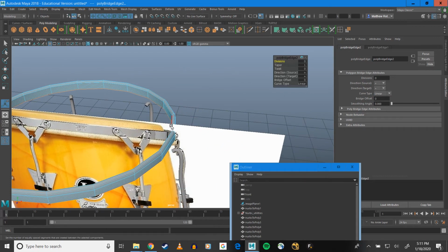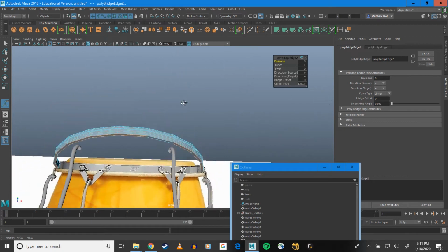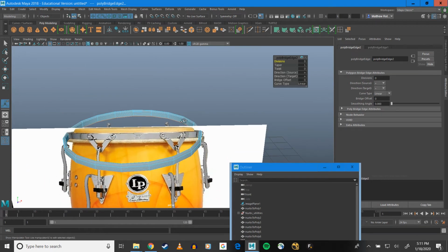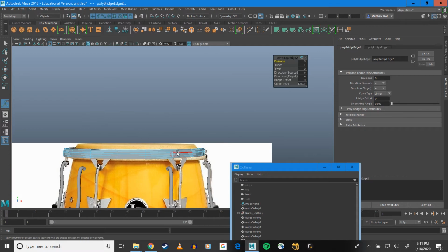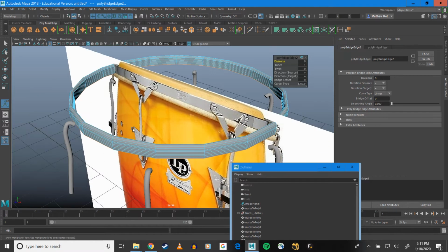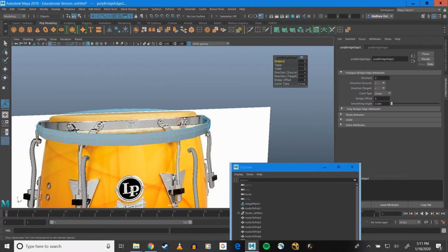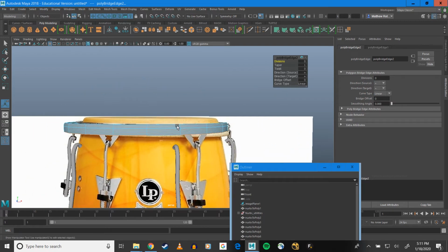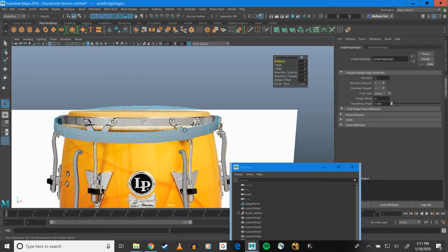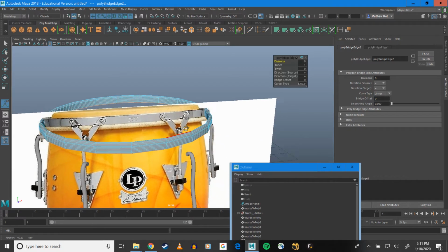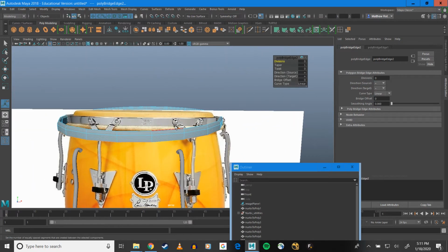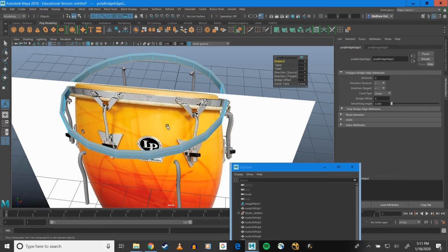And so, now, you can see I can use this to generate the shapes that I need very quickly and edit them very quickly, and I can go back and regenerate them if this isn't exactly how I want them to be. Not that these are necessarily hard shapes to model from scratch using poly geometry, but if you want just to get a nice smooth curve quickly without having to go back and perhaps add your geometry edge loops at a time, which would be more efficient.